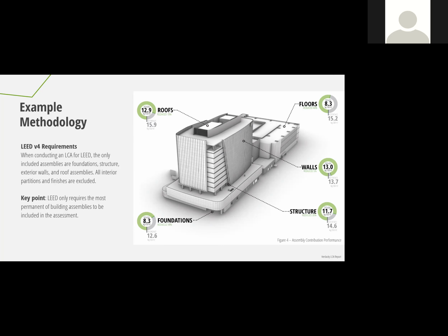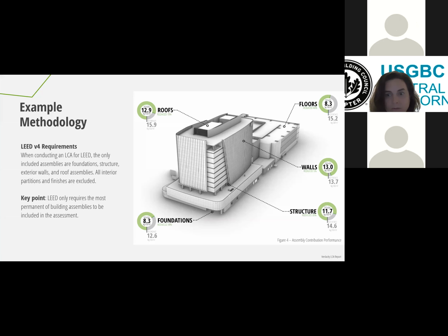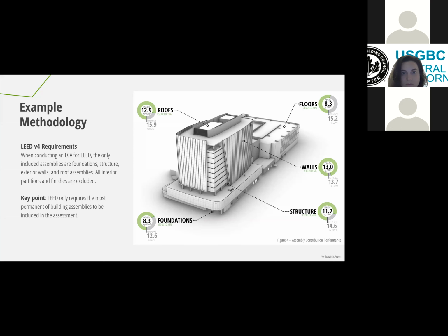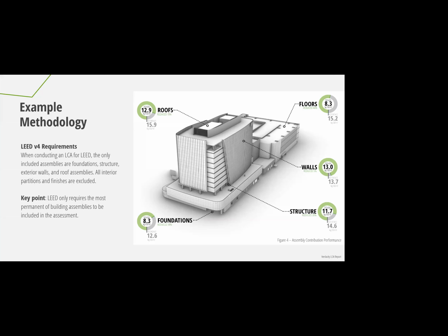And the goal with this is really to focus on the building elements with the greatest longevity in order to create a more accurate assessment. And that really comes down to, when we look at foundations, exterior walls and structure, those things tend to not change much over the course of the life of the building. Whereas if we look at interior partitions, mechanical systems, and especially interior finishes, those things tend to have a much shorter lifespan than that of a building, and will almost certainly be changed out over the course of an entire assessment period.